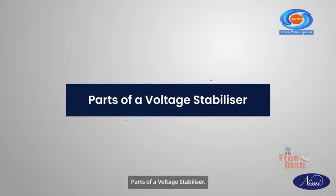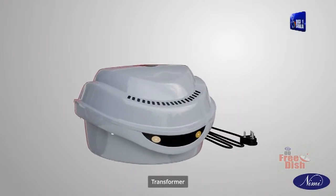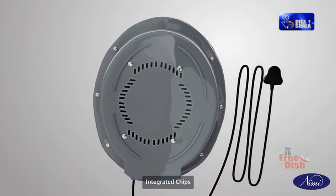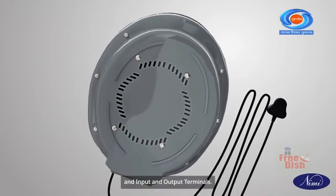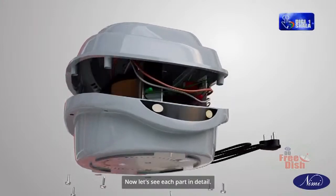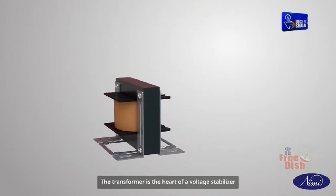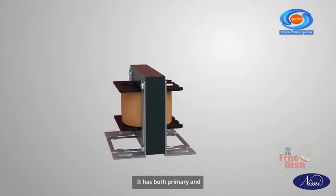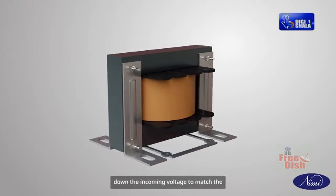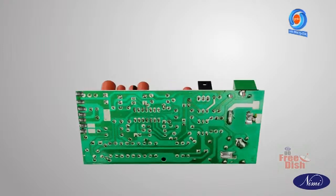Parts of a voltage stabilizer. The main parts of a voltage stabilizer are transformer, circuit board, relay, transistors, integrated chips, preset, and input and output terminals. Now let's see each part in detail. Transformer. The transformer is the heart of a voltage stabilizer. It has both primary and secondary windings. It steps up or steps down the incoming voltage to match the desired output level.